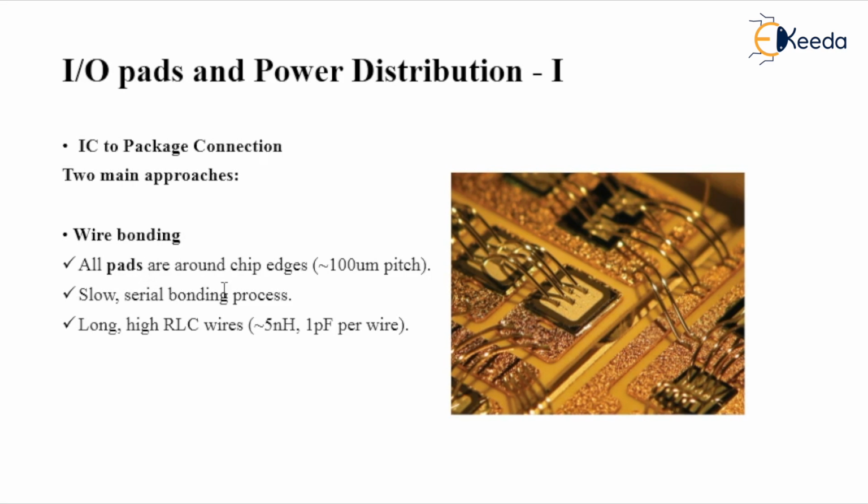Here all the pads are around the chip edges, with approximately 100 micrometers pitch, and this is a slow and serial bonding process, and the values of the RLC of the wires are also very high. If you see, some of the values have been written here: 5 nanohenry is the inductance value of the wire, and 1 picofarad is the capacitance value in wire bonding.